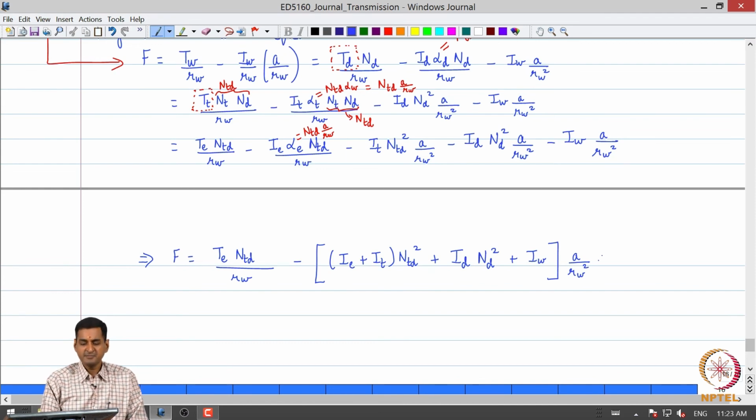So, this is an expression that relates the force that comes out of the powertrain to the input engine torque and the gear ratios, okay, and the inertia of the rotating components and the acceleration, right, of the vehicle. Okay, so that is what we know. Now, here we will put a factor eta t. Okay.